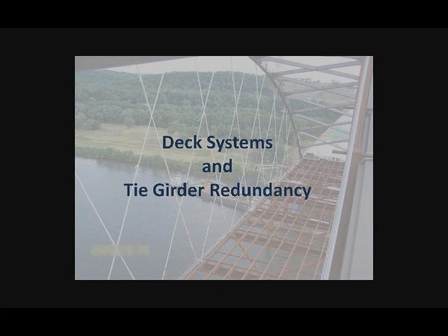I have mentioned earlier that the tie girders are fracture critical. That means if we have damage to the tie girder, if we lose the tie girder, that's bad news. So we try to improve the redundancy of the tie girder so that we have alternative load paths. So I will talk about that a little bit in the context of the various deck systems.